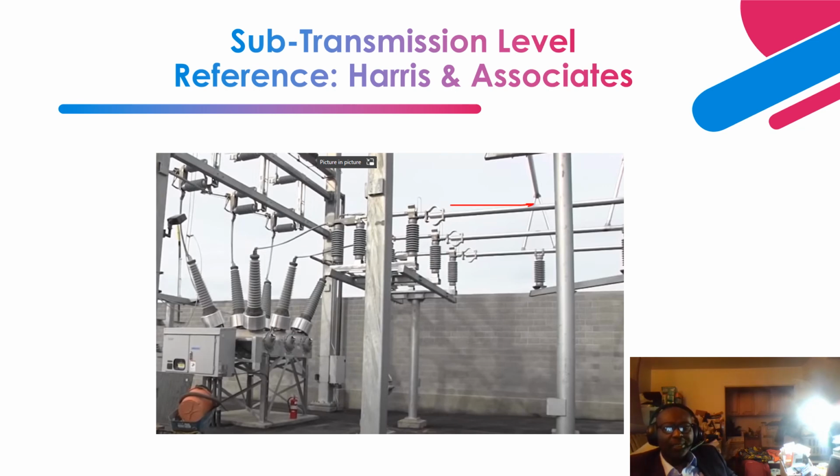So on the side are the tubular bars, which I have explained to you. As you can see over here, there is another arrangement. They call it the hook switch. This is a vertical mounted disconnect switch, basically operating in a vertical open and close mode, and most of these are called a hook switch.